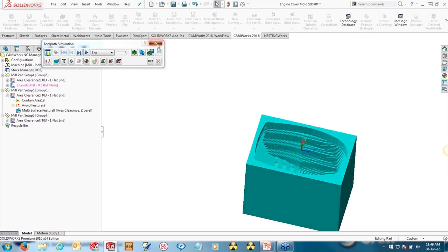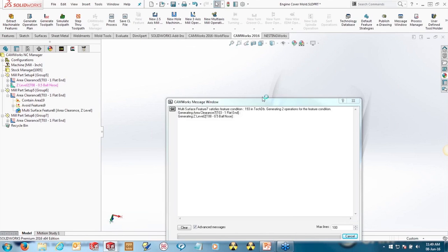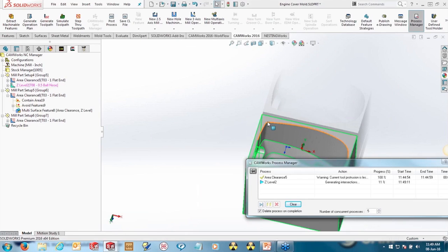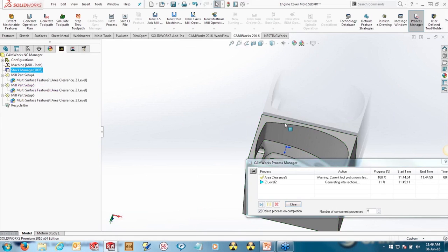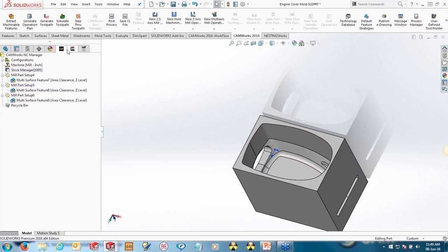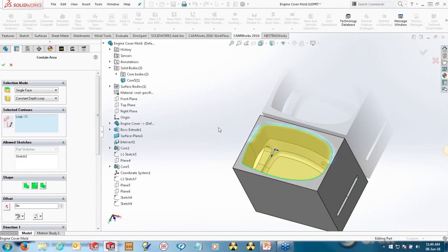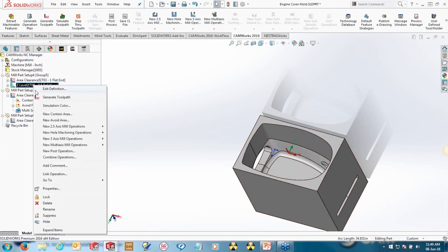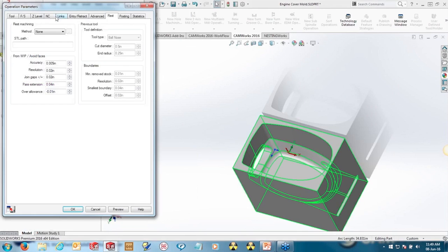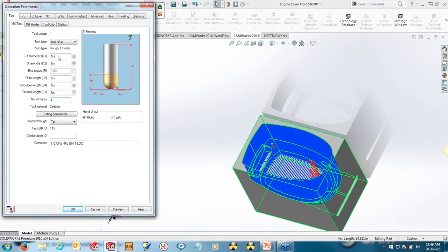But obviously now we want to finish it. So I could use a Z level in this case, but it's going to do straight down. So all those undercuts that we looked at, it's not going to cut in there. So we do need to use some 5-axis. So what I'm going to do is tell it we want to program these. But there are these holes in these surfaces, which if I just generate that toolpath here, if we put in that same container over here, and maybe change the step down as well, so it doesn't take as long to generate here, maybe use a 1-inch ball as well.